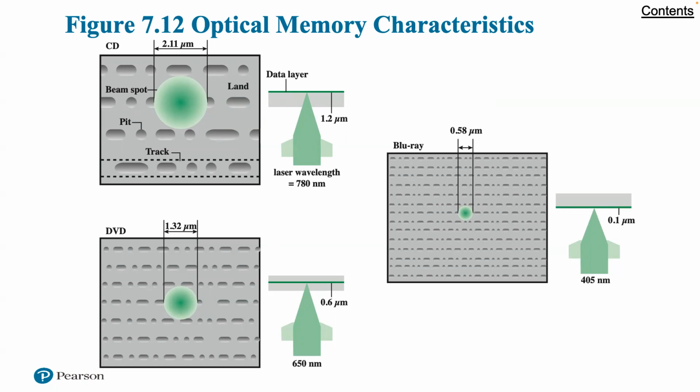The higher bit density is achieved by using a laser with a shorter wavelength in the blue-violet range. The data pits, which constitute the digital ones and zeros, are smaller on the high definition optical disc compared to the DVD because of the shorter wavelength. Two competing disc formats and technologies initially competed for market acceptance, the HD DVD and the Blu-ray DVD. The Blu-ray scheme ultimately achieved market dominance. The HD DVD scheme can store 15 gigabytes on a single layer on a single side.